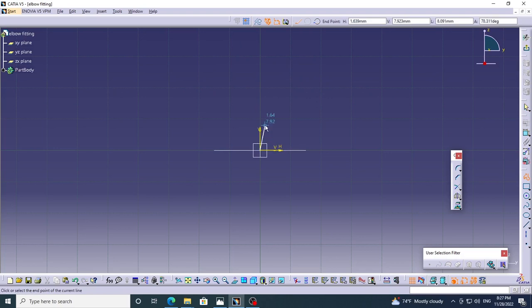After drawing the line, you can click and select tangent arc. Make sure it's blue and it's 90 degrees. When you go right, make sure these two blue parallel lines appear. It means this line is tangent with that arc. Press escape to exit profile.